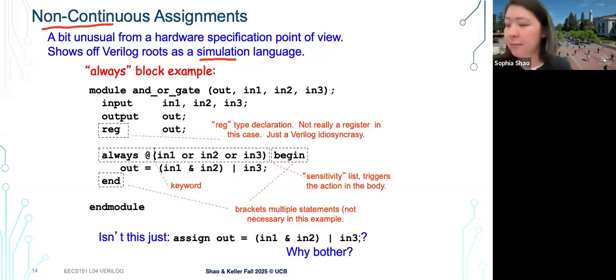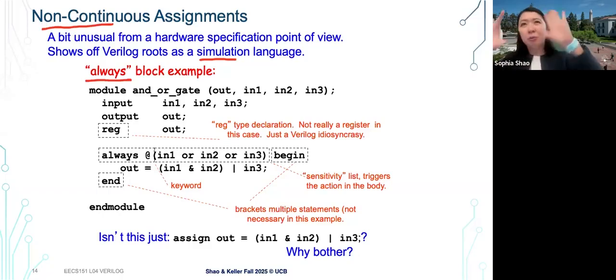One of the most common blocks that you will see in Verilog is the always block. It's actually a little bit tricky. You will see that people design SystemVerilog a little bit differently to separate how you use the always block to describe combinational logic and how you use the always block to design sequential logic. Verilog is a little bit confusing, but it will make sense. We'll talk about the different ways, but the always block can be used to describe both combinational logic and sequential logic. We'll talk about how they are different from each other.